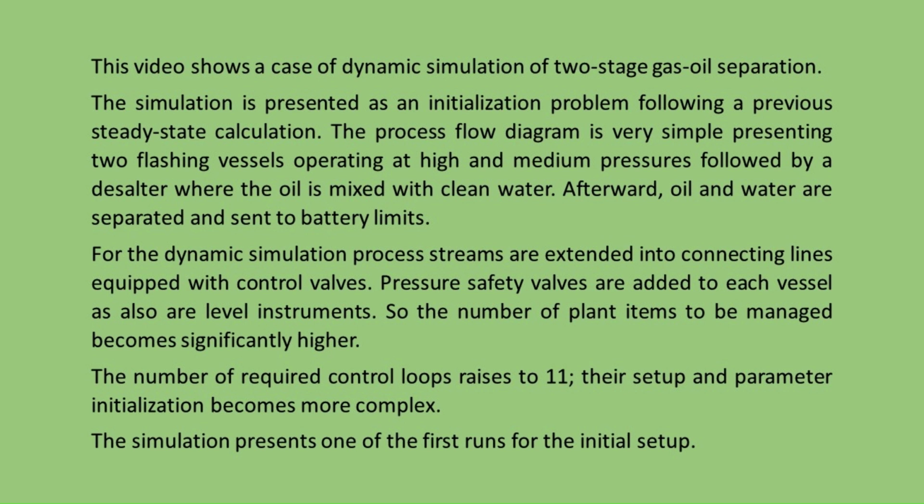For the dynamic simulation, process streams are extended into connecting lines equipped with control valves. Pressure safety valves are added to each vessel, as also are level instruments. So the number of plant items to be managed becomes significantly higher. The number of required control loops rises to 11, so their setup and parameter initialization become more complex.